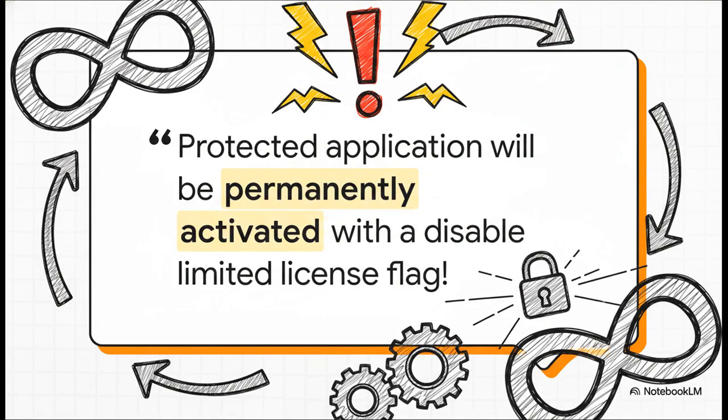Okay, I really want to stop here for a second because this is super important. You have to pay close attention to this warning. When you use that Disable Limited License flag, that action is permanent for that installation. There's no going back. The license is fully, permanently activated.